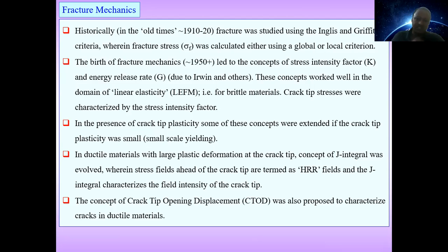In ductile materials, with large plastic deformation at the crack tip, the concept of J integral evolved, wherein the stress fields ahead of the crack tip are termed HRR fields, and the J integral characterizes the field intensity at the crack tip. The concept of crack tip opening displacement, CTOD, was also proposed to characterize cracks in ductile materials.